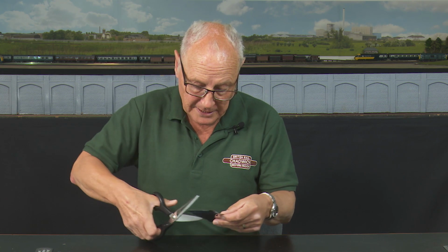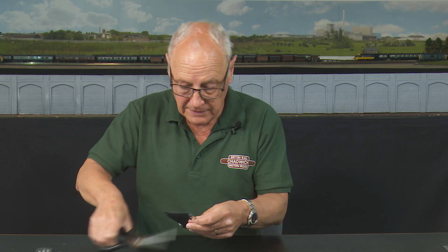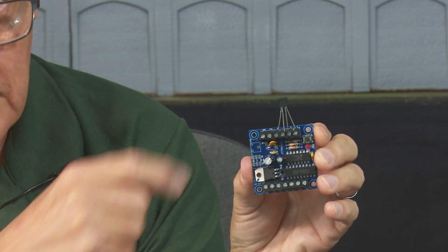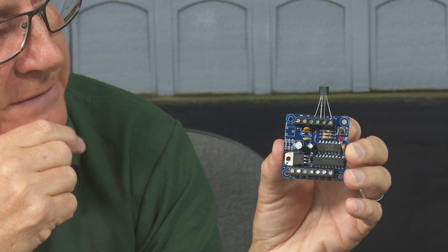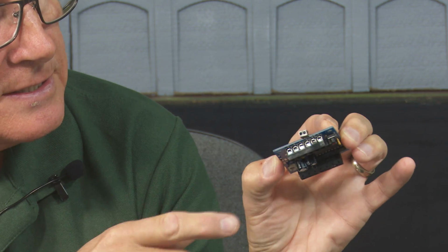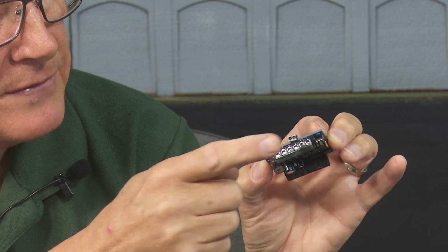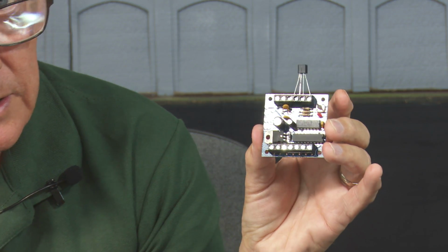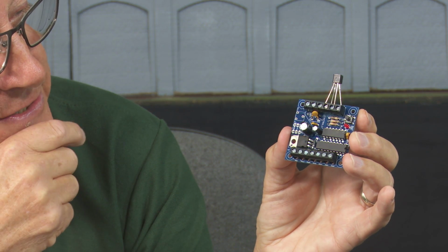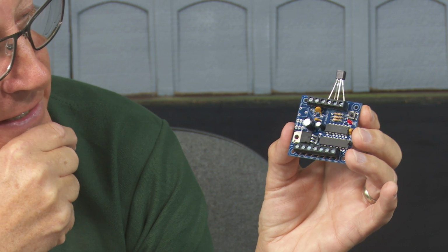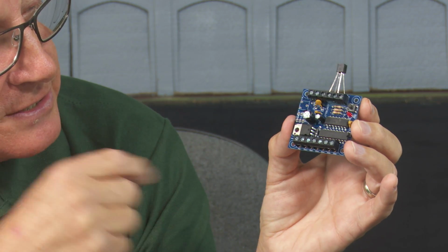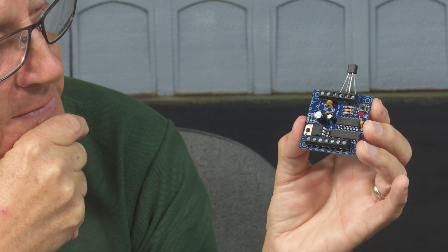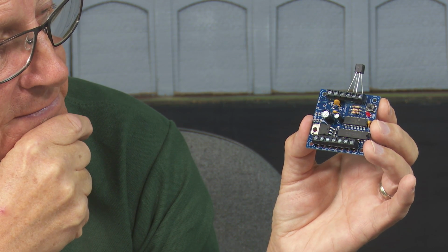And if I open this little packet, what we have inside is a circuit board, and here on the top is this little infrared sensor, and it sends out an infrared beam, and then when a locomotive passes over the top it bounces back into the sensor, and then through this circuit board it changes the signal from green to red, and then over time, that's preset into this, you can adjust this yourself, it then goes to yellow, perhaps to double yellow, and then back to green.